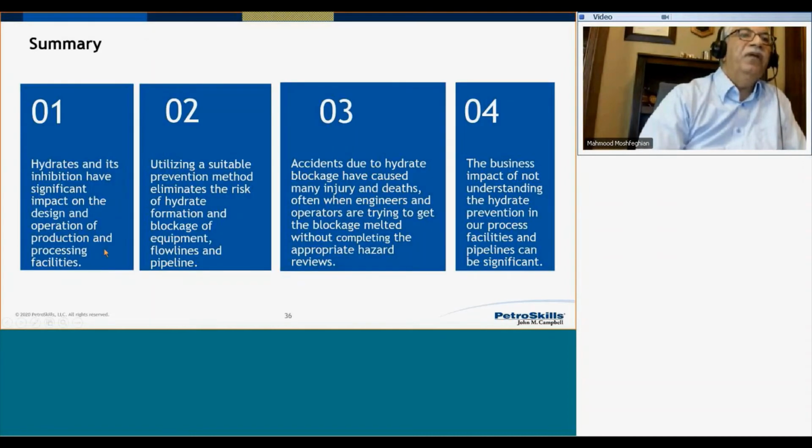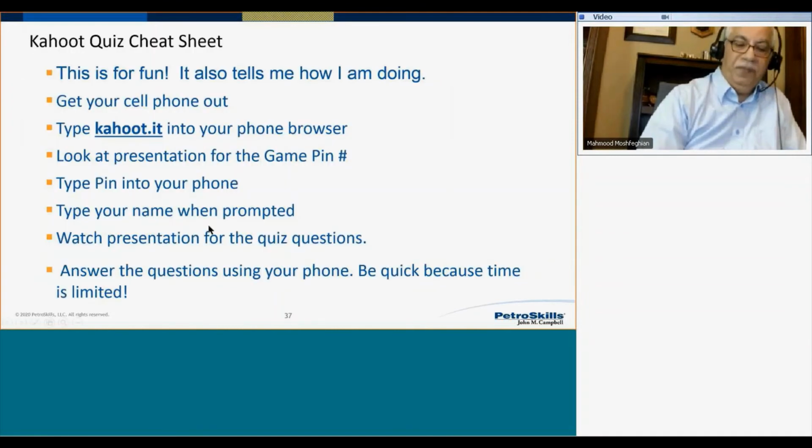So in summary, for our webinar, we can say hydrate and inhibition have significant impact on the design and operation of production and processing facilities. I hope you agree with me on the first one after watching this webinar. Utilizing a suitable prevention method eliminates the risk of hydrate formation and blockage of equipment, flow lines, and pipelines. So we saw several of them, and we have to use a suitable one which works best for our scenario.